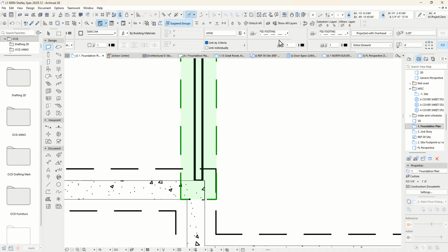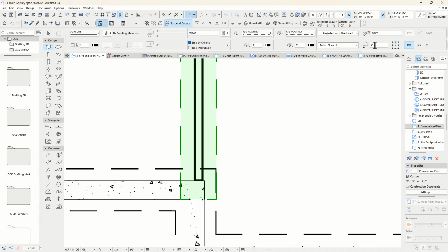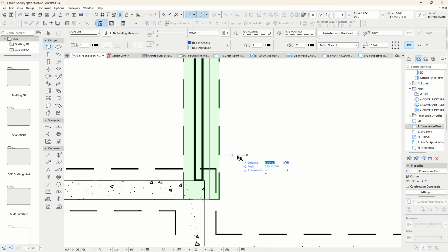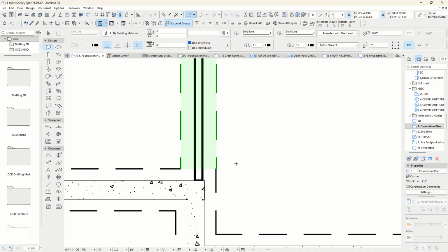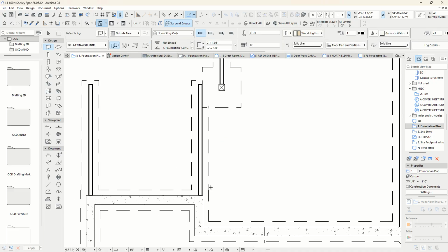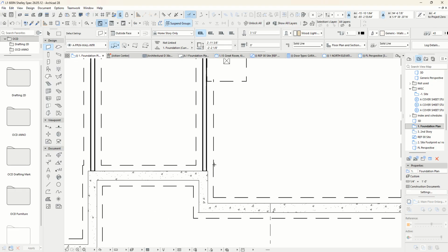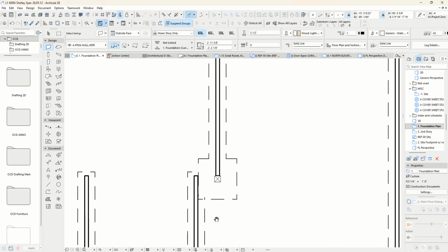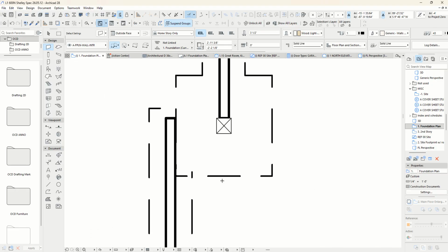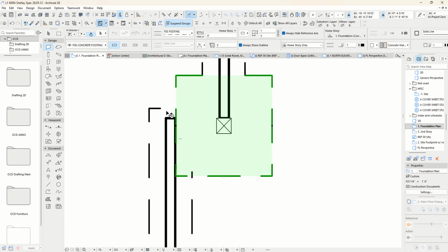Where am I? There it is. So right now it's at 4, so an additional 1.25 inches would be 5.25. Enter. And then of course I have to move that thing over 1.25 inches, and boom, like magic, it trims. Now, chances are in the field they would ignore that 1/4 inch offset and do something else, but I'll let them do that. Now in this case, these lines don't merge.